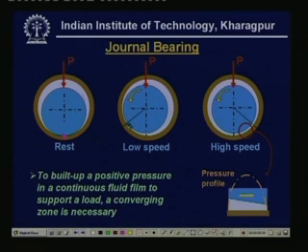What I mean to say is that in this particular case, almost metal to metal contact will be prevailing, and some sort of oiliness will be there if it contains oil, as I told you. If there is no oil, then there will be purely metal to metal contact, and in case of oil presence there will be just an oiliness; the entire journal will not be lifted up by this oil.